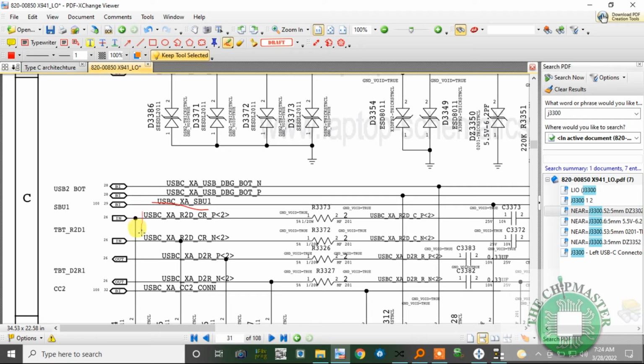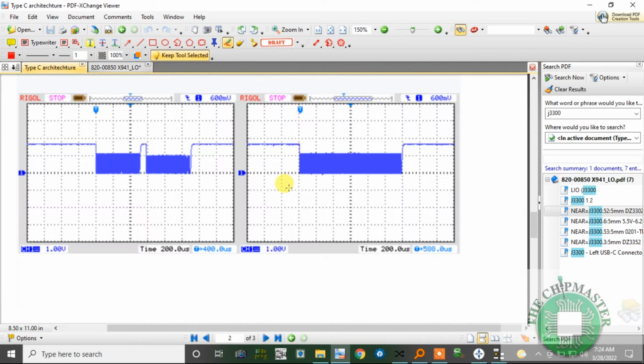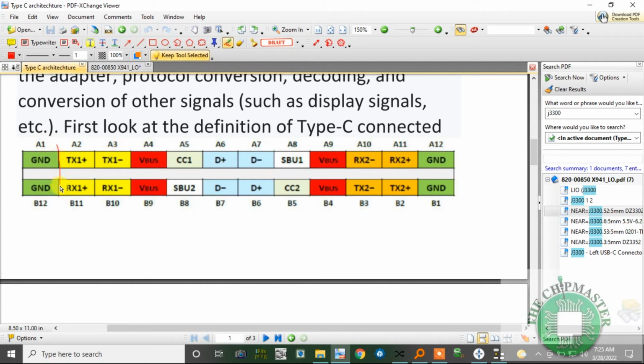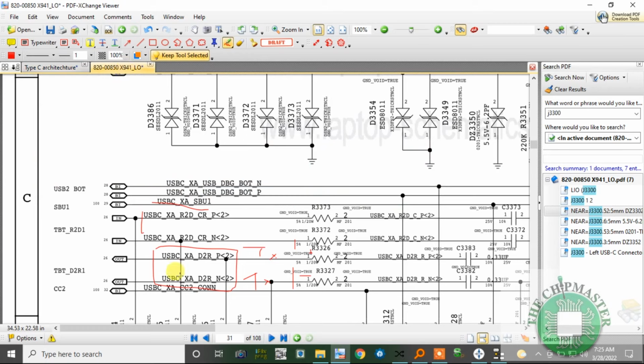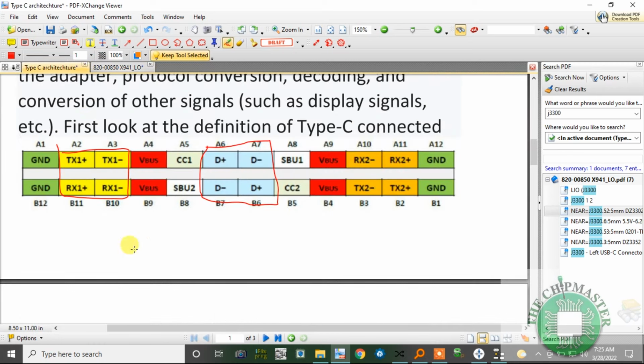This is USB-C, positive and negative, and this is the differential signal, TX1 positive and TX1 negative. That was my mistake. I forgot that there is a differential signal line on the USB architecture for this part. This is the section that is just highlighted, negative and positive, the USB 2.0, USB 3.0 section. This is the TX differential signal, used to transfer display signals or for expansion purposes, such as expanding your LAN, VGA, or HDMI. All that signal is passed through this section.